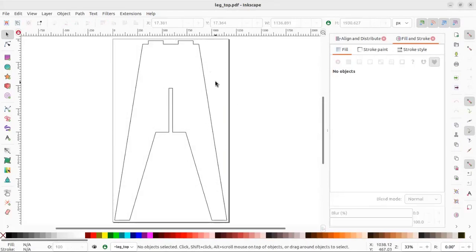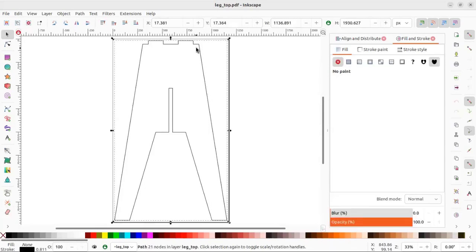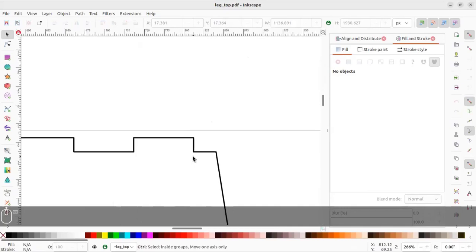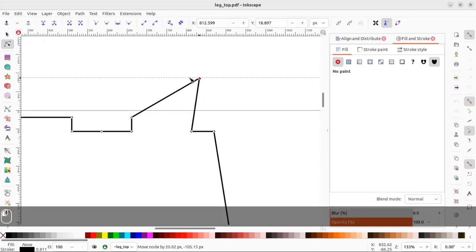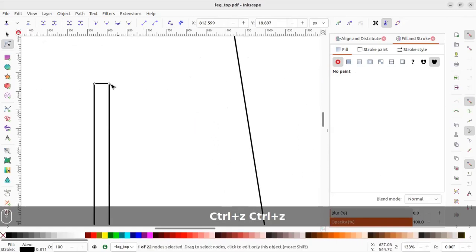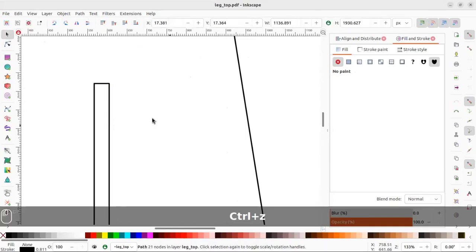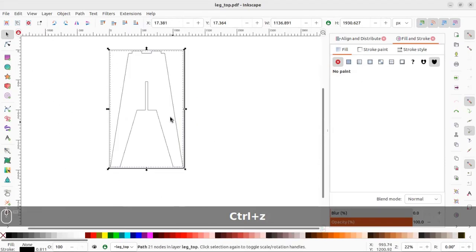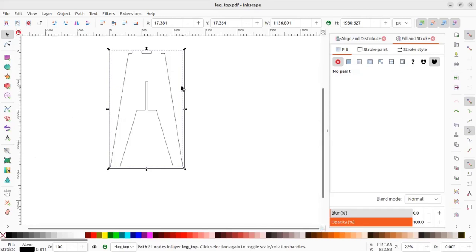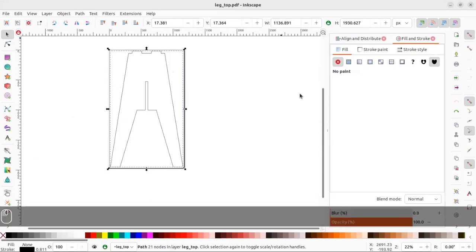What is really great about SolveSpace and this export of drawings is that it actually creates closed shapes. So sometimes with Fusion 360 and with FreeCAD, you end up with having these lines separated, and it's a huge pain when you are trying to laser cut lines that are separated. So SolveSpace generates really nice drawings, closed shapes, no problem at all, as you see. And that makes the whole cutting process much easier if you have drawings that are actually closed.